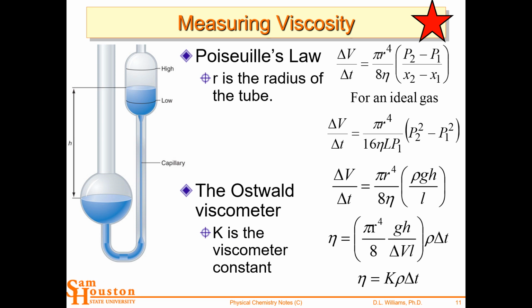And that is, whenever you've got a 5-gallon bucket of solvent, like I have typically down in the bulk solvent area, don't try to pour that into a beaker or into a gallon jug or whatever, because the hole is not even at the edge of the container. It's going to glug and splash everywhere. So you siphon out of those. So you get a Tygon tubing.